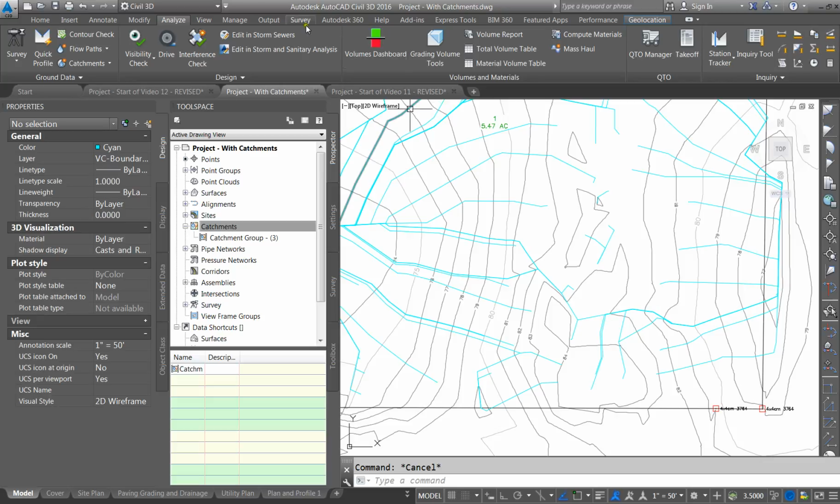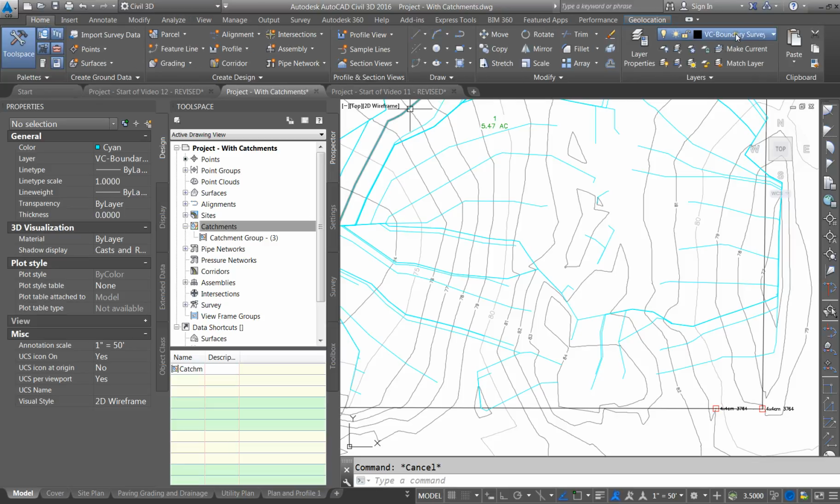As I move through here, I can find basically the ridge line where the water goes from one direction to the other. So I can come in here and just create a polyline, and make sure I'm on my proper layer, pre-basin. I'm going to do a polyline, and I can start building where I think that drainage basin will go. I need to change that to by layer.